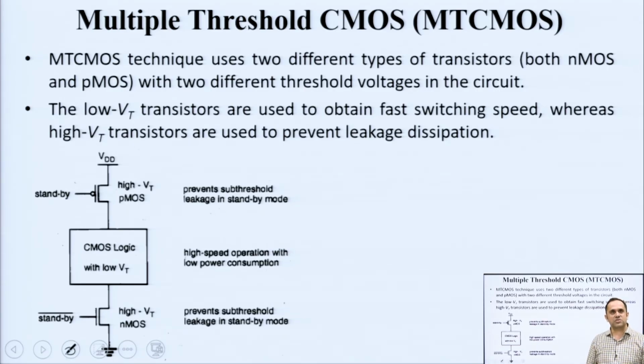Since you are using low threshold voltage for your circuit operation, you can reduce delay, and you have the liberty of scaling down your power supply, which helps you achieve your low power VLSI design. At the same time, you control your subthreshold currents. So, in the standby mode, when this is off, and when we say standby mode, we mean the standby mode here.